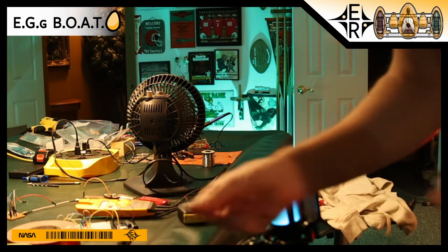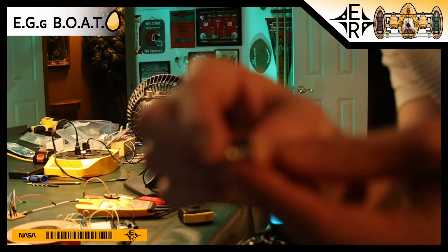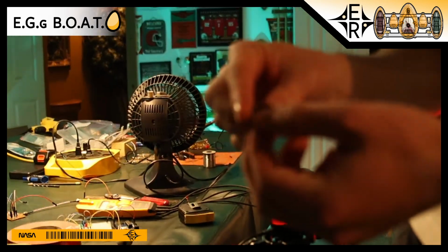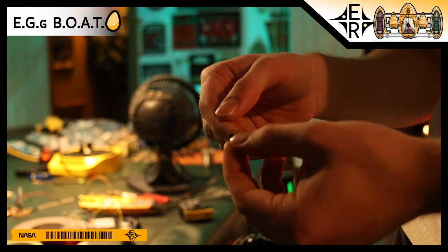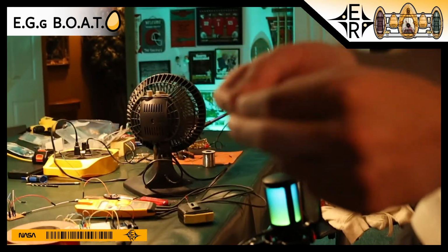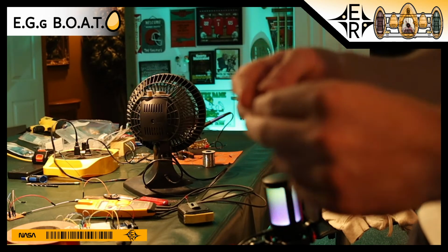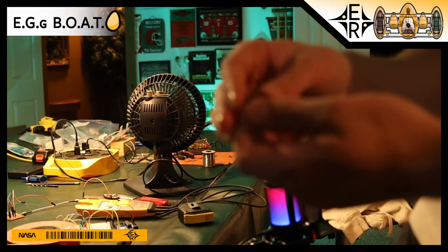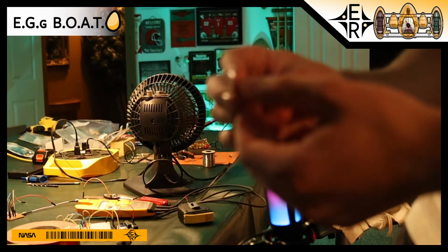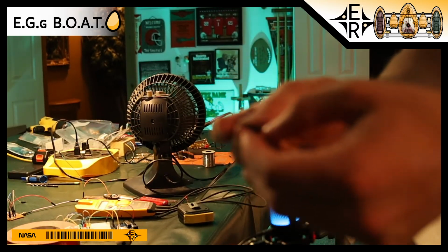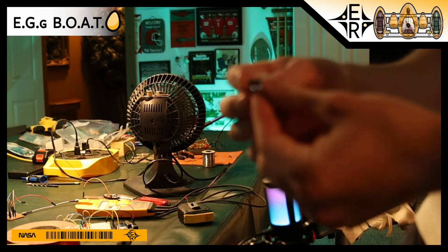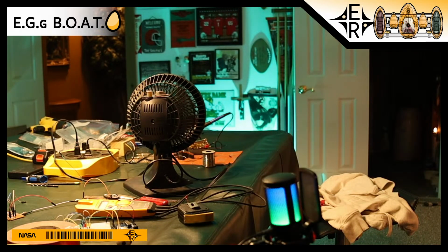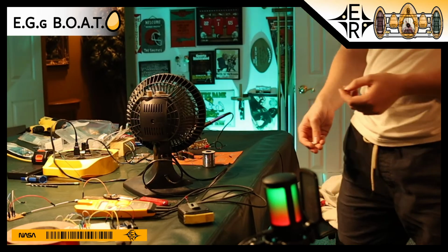Taking these little pin headers and just soldering a bunch on the bottom ones all together so that they're all electrically connected. Kind of a hacked way to do it, not very professional, but it'll work for testing. Then we can take the single power output pin from the Arduino, attach to one, and use the other four to get power for each of the four individual circuits. So doing that with both the power and the ground. That's how we'll be able to power these for testing. And once everything works, obviously we'll get a more robust system going.